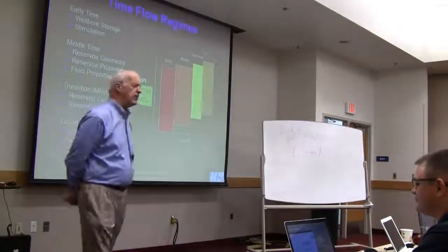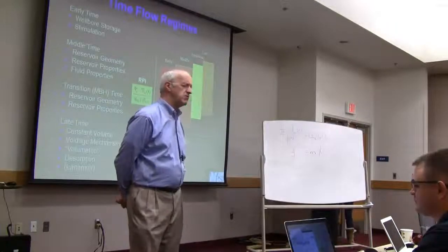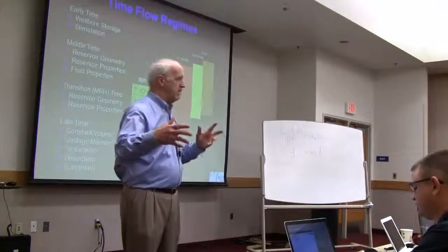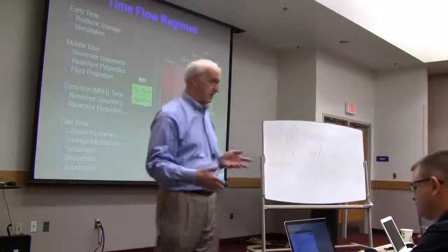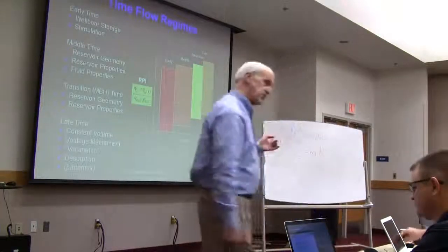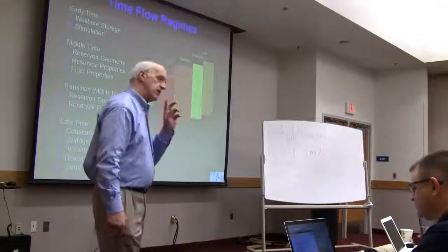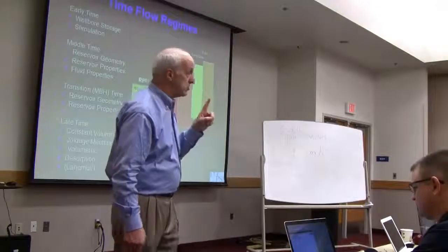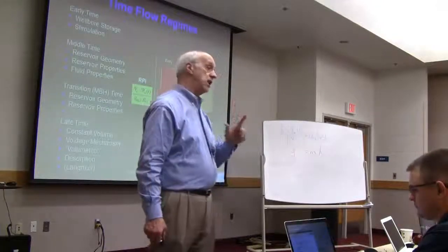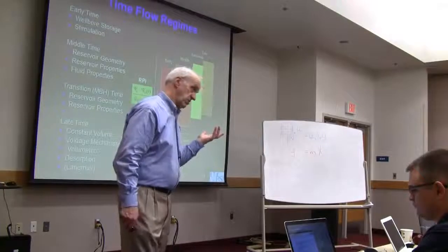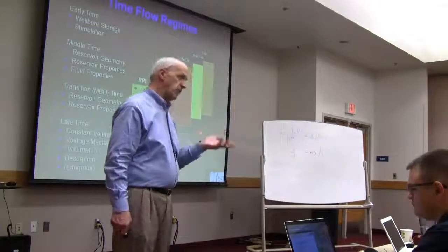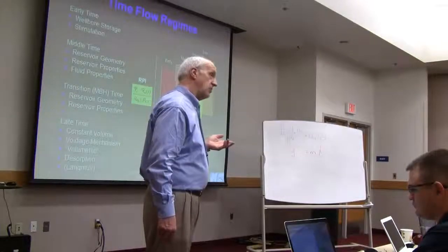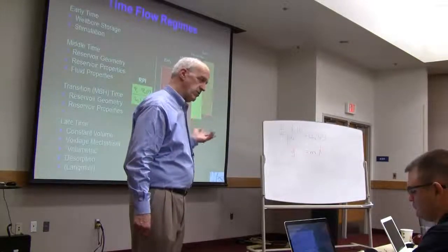I hope one of the ideas that's beginning to wrestle its way into your head is this idea that a well's history is a path. That's why I ended my conversation a minute ago with you about the idea that thickness changes. That thickness which controls a well's behavior changes as the well ages. Right? I dare say that question had not been raised to you before. 10 years ago, I wasn't smart enough to raise it. I hadn't thought this process through.